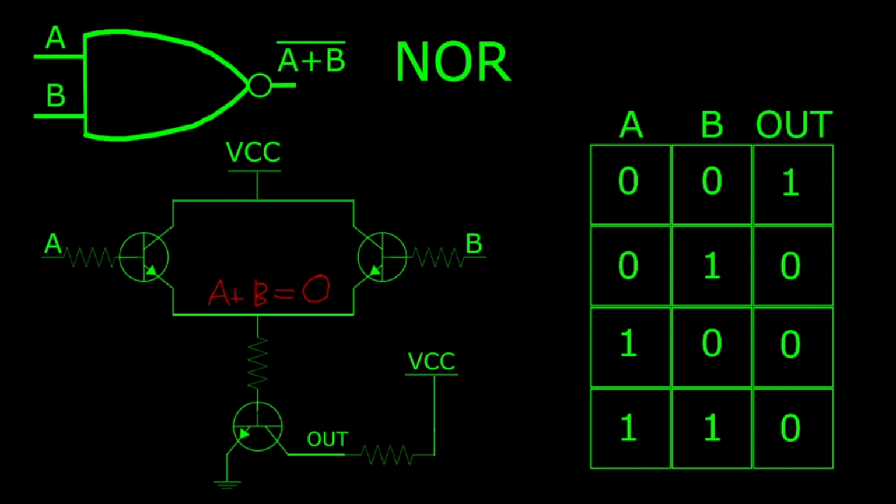Let's say, on the other hand, both of our inputs are equal to 0. That will turn off the transistor in the NOT gate because there's no current flow through the base. And because our output can have no current flow due to the high resistance in the transistor, the voltage drop across the output resistor will be 0 volts, so our output will have a high voltage.